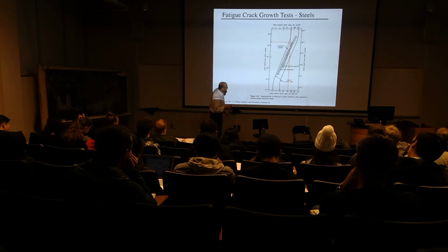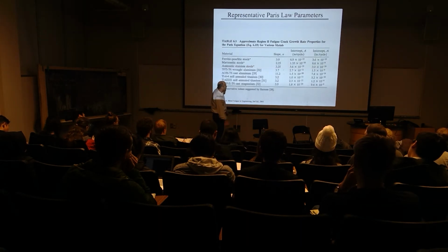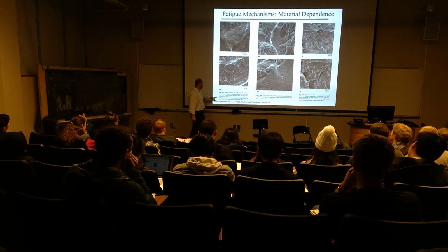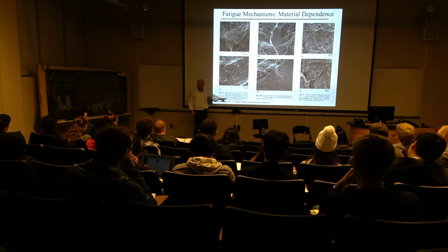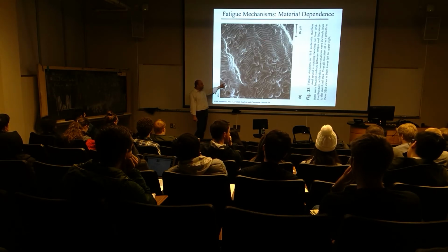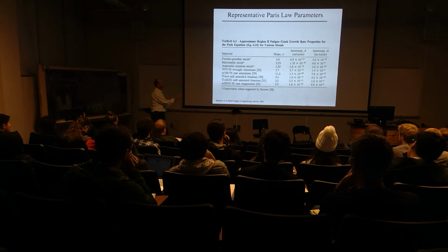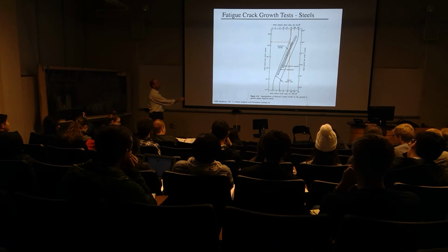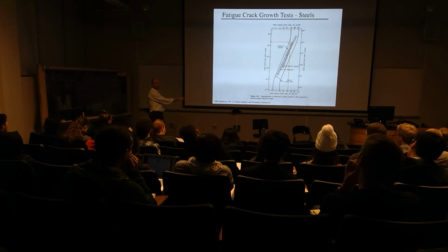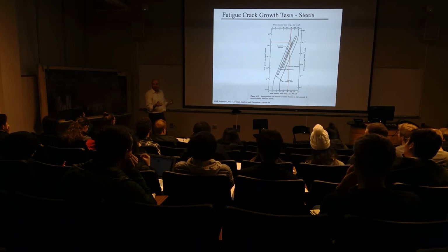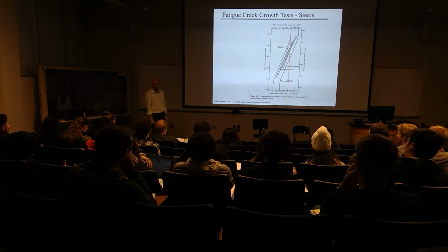But the other thing is, if I go back to that figure, and rather than read this way, I'm going to read this way. It says here, B, core striations were located closer to the overload area. That means closer to where the material was undergoing or going to undergo bulk fracture. And so when I see it, I go back here and I predict what's going on. When I look at that response, I estimate 55 megapascal square root meters. There's almost no data there. What does that tell you? The data doesn't exist because that crack's no longer growing cyclically. It went unstable. This is just too exciting. This is like, wow, I get paid for this stuff.